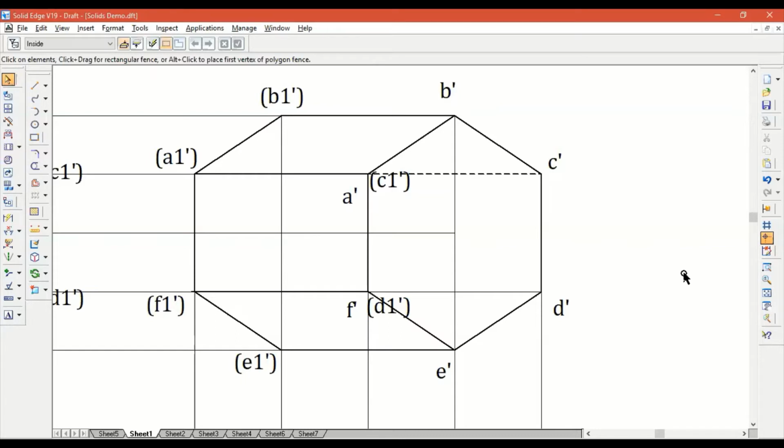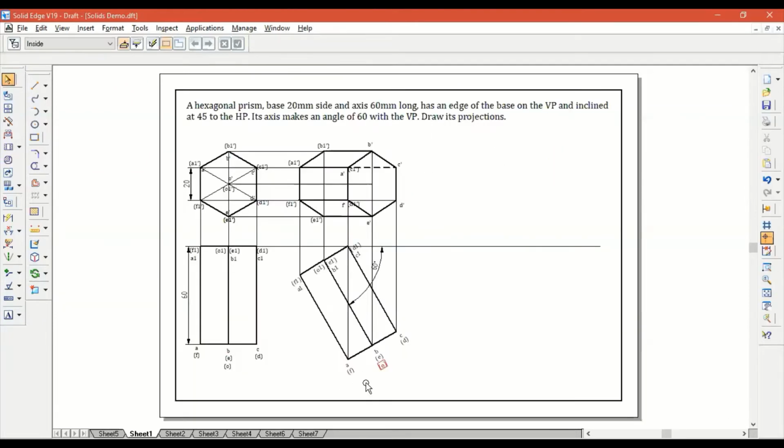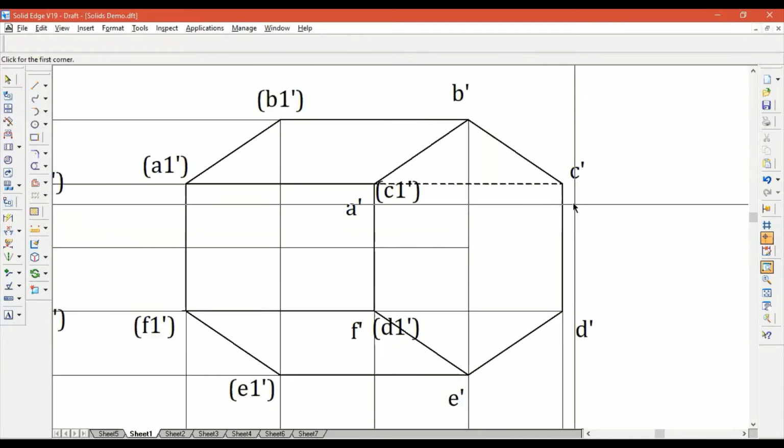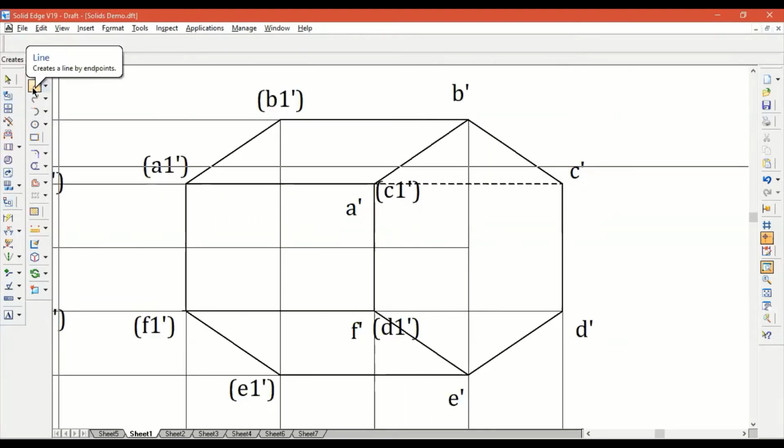Either you have a line behind a visible base, like in our case right here, where we know that the point A dash, C dash is visible, but we also know that the point C1 dash is invisible. The reason C1 dash is invisible is the observer looking at it from here definitely is going to realize it is going to be furthest away from the point C1, which is part of the base on which the object is resting. So C1 is invisible, whereas C is visible. That means the line through that is definitely going to be invisible.